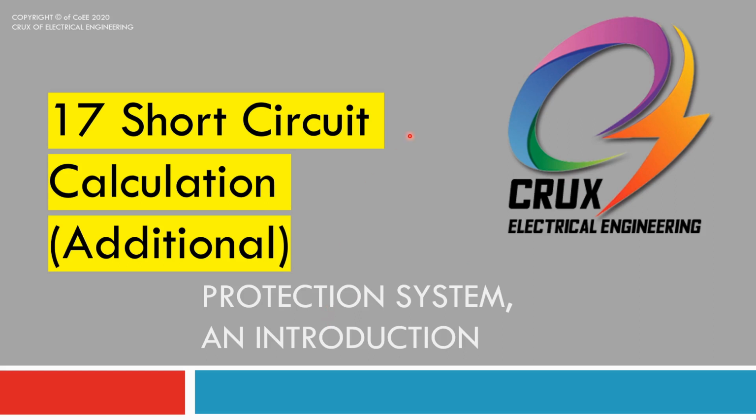Alright, so these are additional notes. This might be useful even for university students who are just starting to learn Power System 1, in terms of the per unit method for balanced fault only. For unbalanced fault, this is not the method. For unbalanced fault, you have to use the conventional positive sequence, negative sequence and zero sequence impedance.